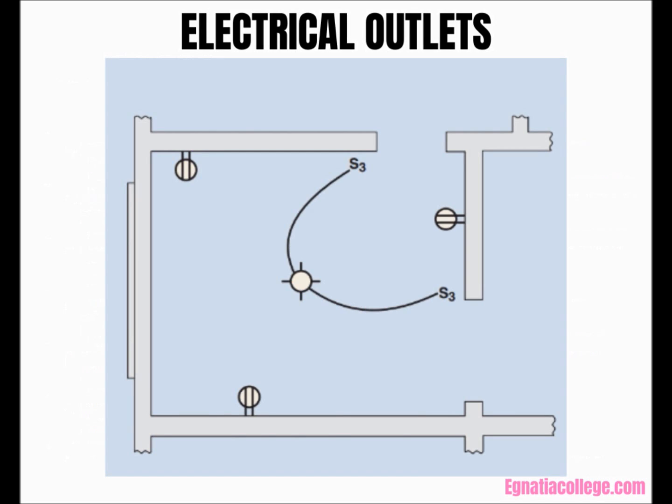Electrical outlets. The Canadian Electrical Code, CEC, defines an outlet as a point on a wiring system where current is taken to supply utilization equipment. The type and location of electrical outlets used for an installation are shown on electrical floor plans. A toggle switch is not an outlet. However, the term outlet is used broadly by electricians to include non-current consuming switches and similar control devices in a wiring system when estimating the cost of the installation.